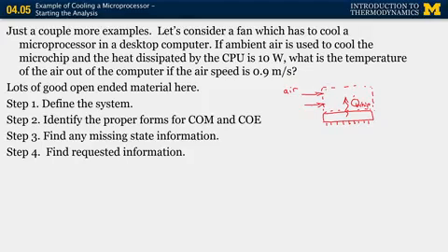Well, you know that to a certain extent, imagine if you have a little box heater, a little flat film heater. A certain area above that heater, you're not going to feel the heat transfer from that heater. It isn't going to be observable in that air. So that's probably your upper bound, where the temperature is unaffected. That is where the upper bound of the control volume would be.